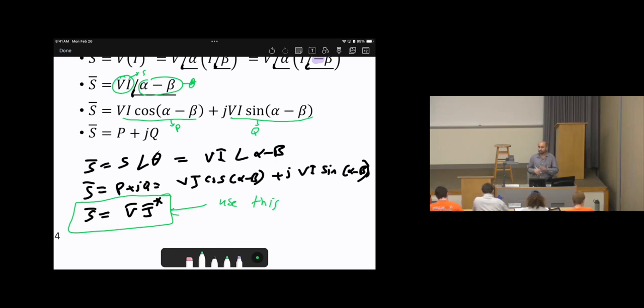Then do the conversion. What you need to know is, if we say find P, P is the real part, Q is the imaginary part, theta is the angle in polar, and S alone without a bar is the magnitude in polar format. That's what you need to know: S angle theta or P plus JQ. Other than that, you know how to do the conversion between polar and rectangular and vice versa. Okay, is this clear?